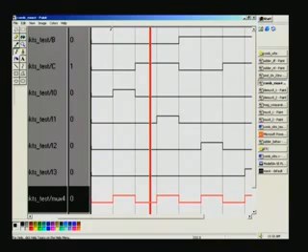So now let us say for 0, 0, if this is the select pin for the MUX, a 4 input MUX, naturally there are 4 inputs, I0 through I3 here. And I0 is the very first one. It corresponds to BC being 0, 0. For the 0, 0 input, I0 must be selected. That means the MUX4 output should be the very same as I0, and you can precisely see that to be the case. See the very same waveform here, and no other waveforms are there in any other inputs. So you can very easily infer that this MUX4 output is clearly due to the input I0. That's precisely what you have here.